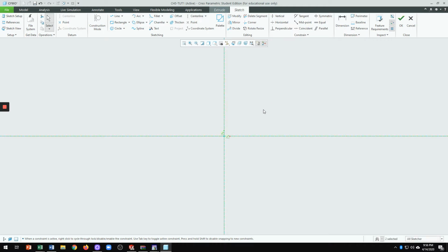All right. So now we remove. We're trying to go to the next step, so we just terminate that command called center lines. At this point, we have a symbol here called collinear lines. When you put a line on top of another, like a center line or solid line, we call it collinear. The center line was positioned on top of the reference line, not the datum, and that center line is also called a construction center line. Okay, all right, nicely done.